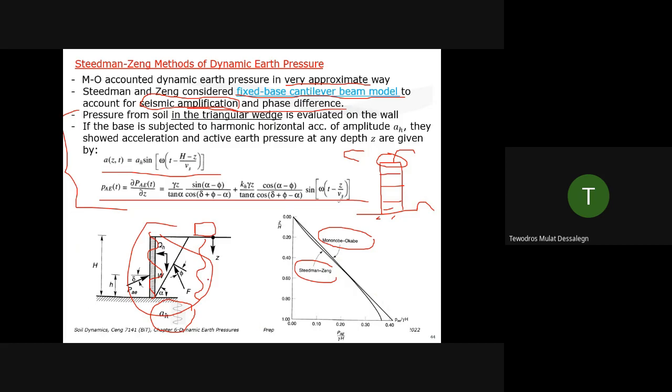So depending on the soil type, do you remember the impedance ratio we discussed in chapter 3? Depending on the impedance difference, there can be amplification, de-amplification, or no amplification. And it's not only impedance, it's not only material difference, even height matters. Because with height, your soil spring changes. The period changes. And you never know, the period may get close to the input motion resonance frequency. So when you start, you may pick an acceleration here, but by the time it's amplified, going through the soil, it may be very close to the resonance state.